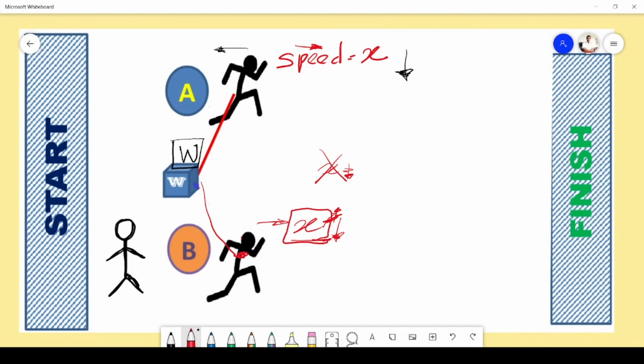That is why I explained previously that the voltage and frequency should be slightly higher, because both the voltage and frequency of a generator depend on the speed of the prime mover. So to have slightly higher voltage and slightly higher frequency, we have to run the prime mover at a slightly higher speed.